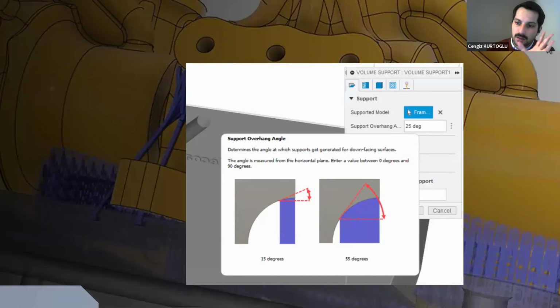Well, as a second technique that I'd like to mention, material jetting works like an inkjet printer, and a nozzle jets the material onto the build platform, which hardens. This process is repeated layer by layer, and these machines vary in complexity and accuracy, but benefits include very low waste of materials and the ability to create multiple parts and colors in a single printing.